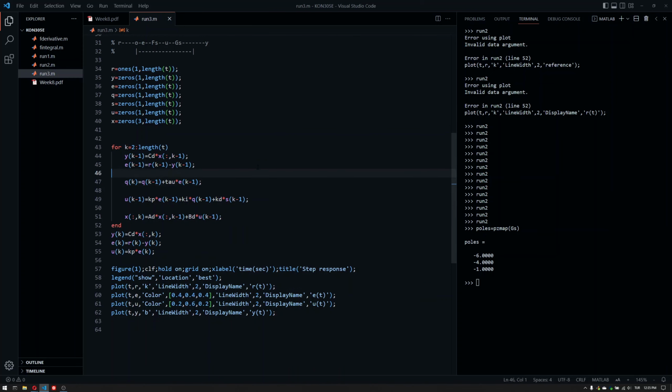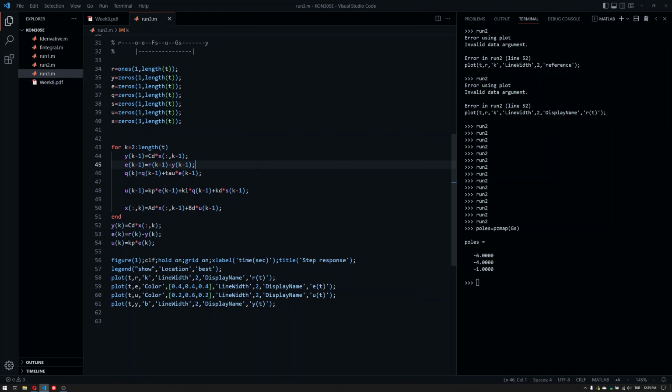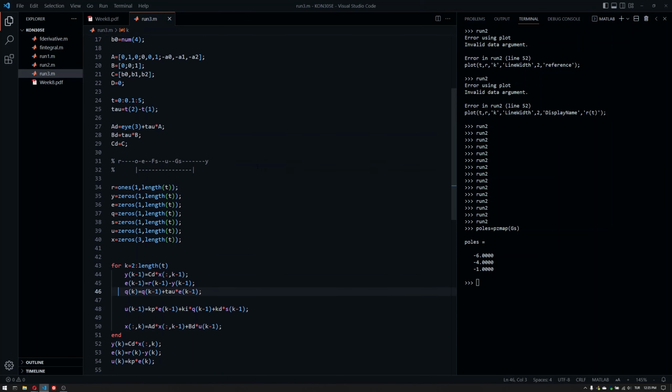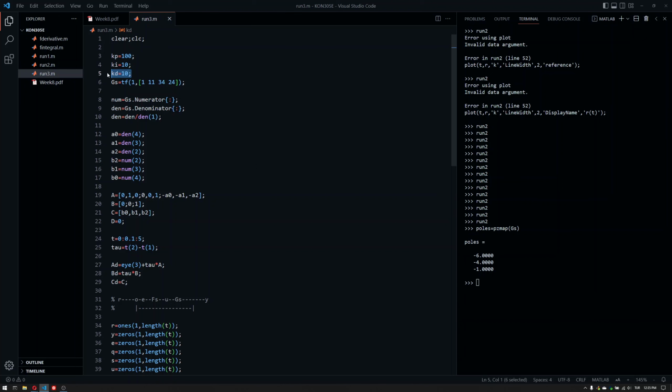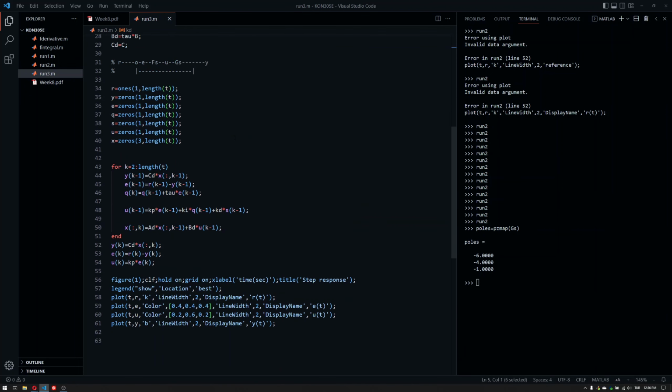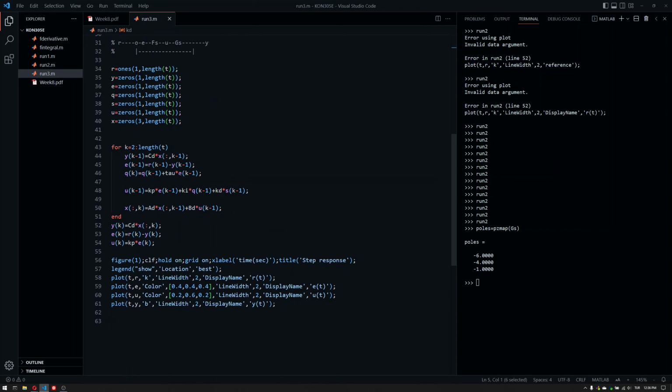You can stop here and drop KD in order to calculate a PI controller, because KD is not implemented yet. But if you keep KD 0, this would be the PI code here. Of course, this is the dynamic part, so that's not necessary to add. Yeah, this is essentially PI. Now, but let's add the derivative part here.